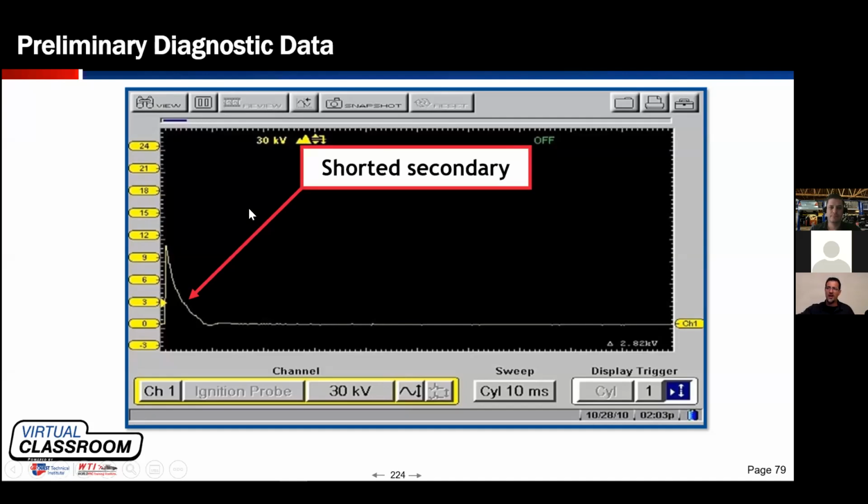Now, anybody that recognizes ignition waveforms will see that spark discharge, I've got about 10,000 volts here, 10 kV, meaning my coil was able to saturate, right, take on energy and build a magnetic field. It was able to collapse and induce a voltage through that step-up transformer that an ignition coil is. And there was enough energy to overcome secondary resistance to create 10,000 volts. But shortly thereafter, this voltage dissipated to ground. So that tells me quite simply that there's a short. This spark is not firing across the spark plug gap as it should. It's finding a path to ground elsewhere.